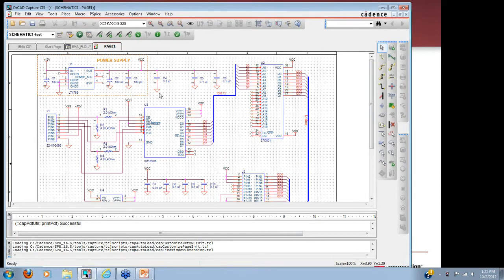With the Status Display app developed by EMA, designers using Cadence OrCAD Capture now have the ability to highlight parts in their schematics based on the company part status field or property. With this feature, Capture users will be able to avoid errors and quickly identify the status of parts on their designs by color, giving teams an effective visual indicator to make sure unapproved or obsolete parts are noticed and not spec'd into the final design.